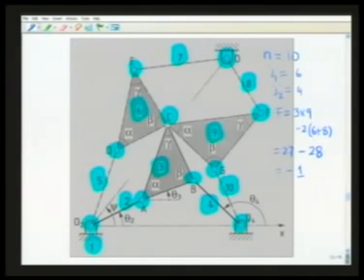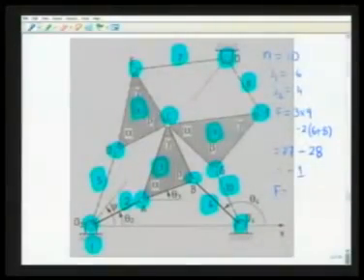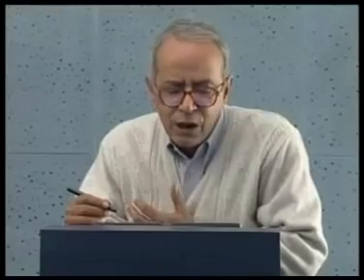Not only that, these ternary links, that is number 3, number 9 and number 6, are similar triangles as indicated by the angles alpha, beta and gamma. Due to the special dimensions, we will find that the degree of freedom of this assembly will become equal to 1. That means this is another example of an overclosed linkage where some of the constraints may be redundant.